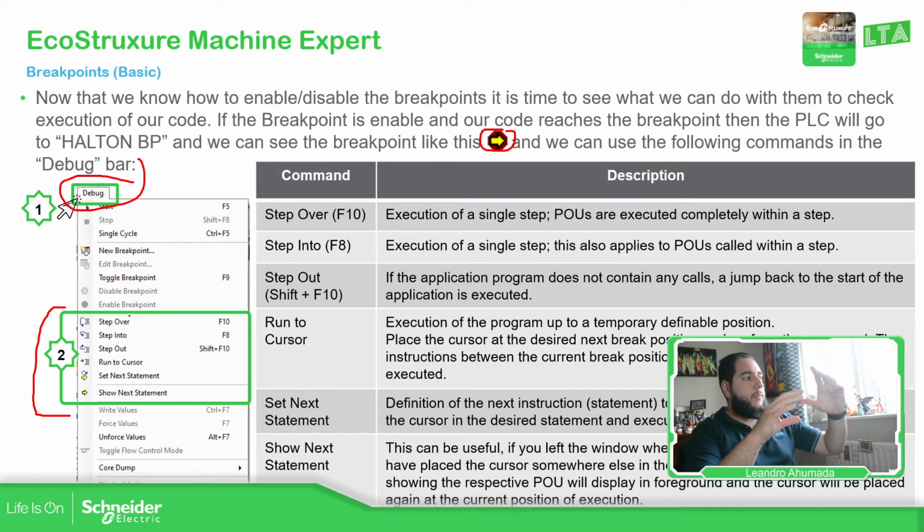Step into allows you to go inside the code and see what's in there, and you also have the possibility to step out to go back to the previous one. Step over just doesn't go inside the POU. If I'm not wrong, this is how it works.